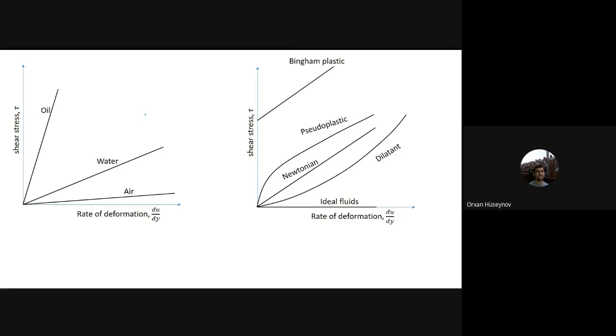the answer is, you have finished your 2 minutes. The answer is the first oil, it has a higher viscosity than the water and than air. The reason is, you can understand it, this one is du dy, and this one is the tau. And we have said that tau is mu into du dy.